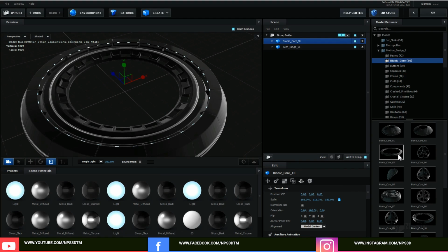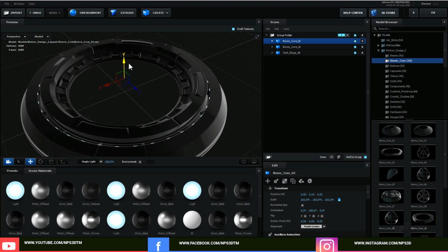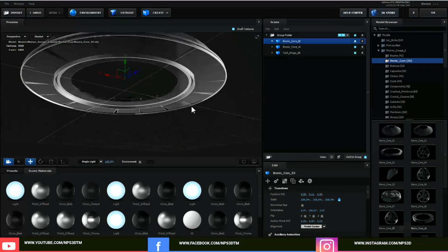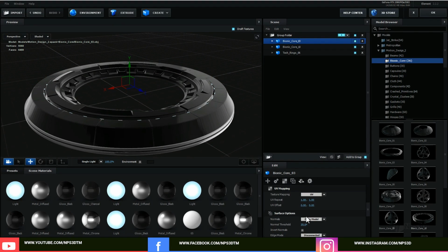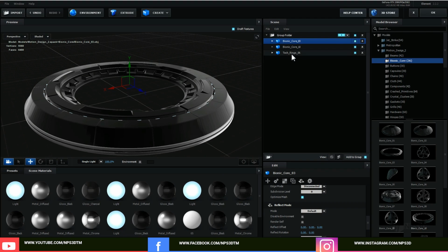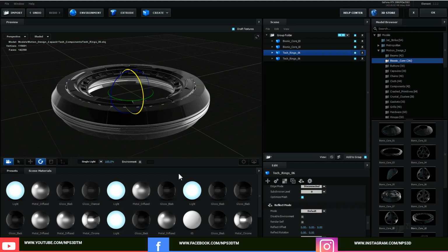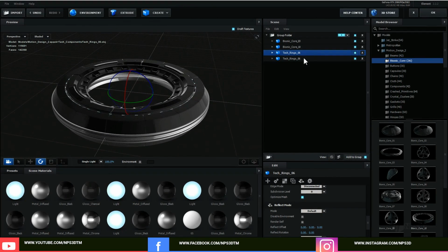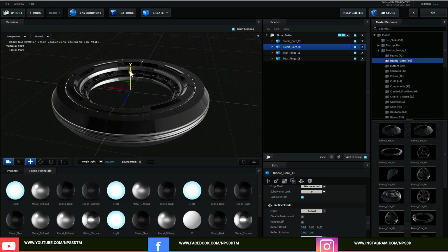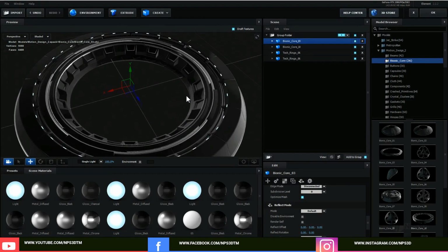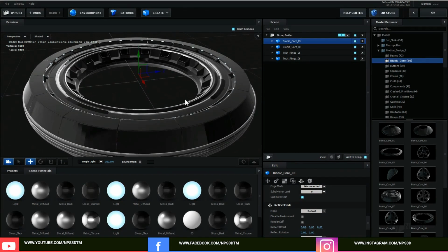Let's bring in another Bionic Core 3 and scale the size and make it here or here, something around here. So it's good, right? Make sure this also has Optimize Mesh checked, and select this last one, duplicate it and rotate it like this, right? And now we can set these things accordingly. So this is good for me now. We can also change all things later, right?